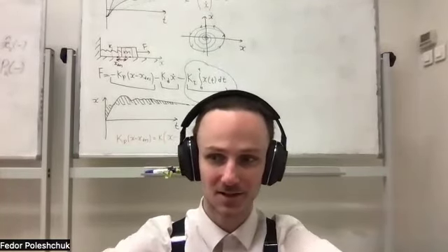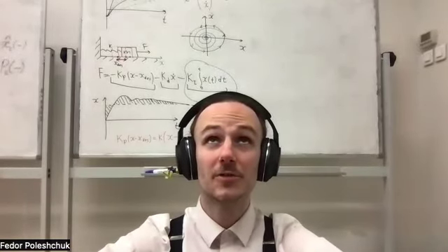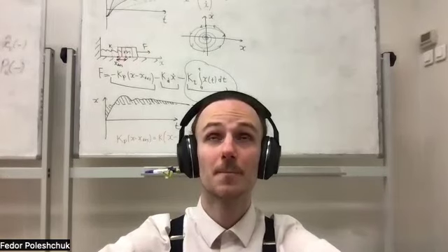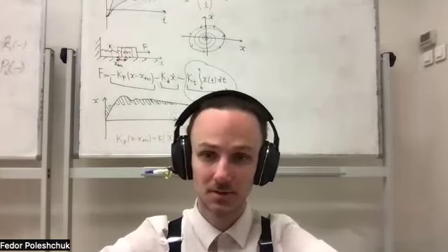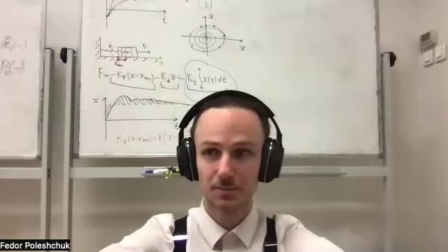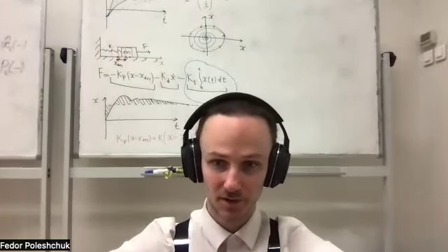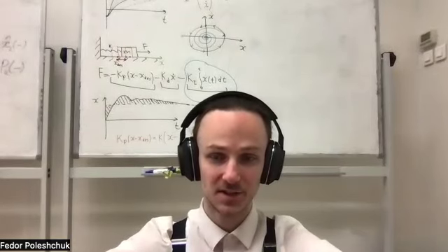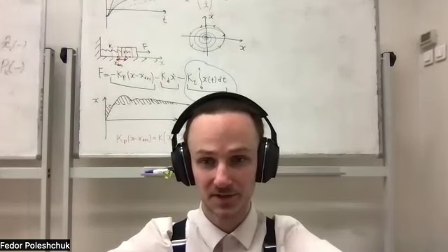The linear quadratic is, I could say that it's really more applicable for higher dimensional systems. So is it more responsive? Is it easier to design? What's the catch? It is a controller that accounts for the model of the system. So it needs the state transfer function. We have to understand the dynamics of the system.